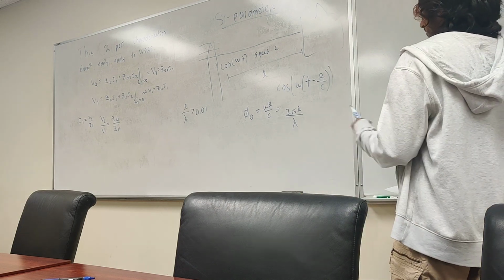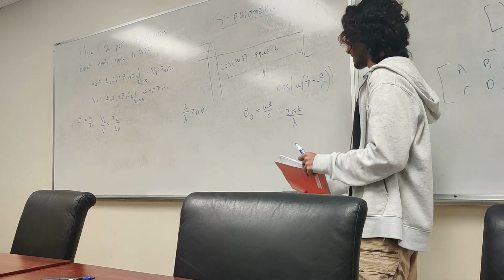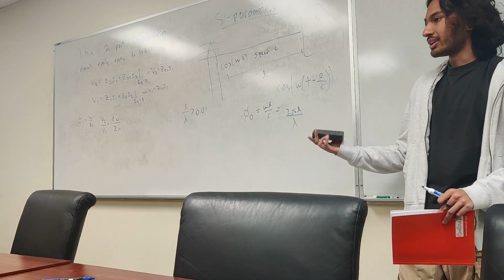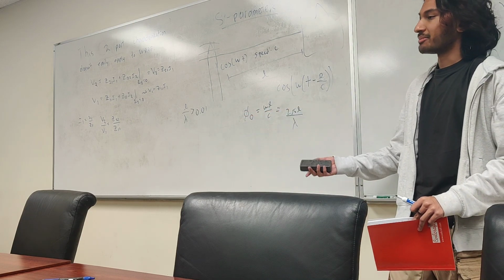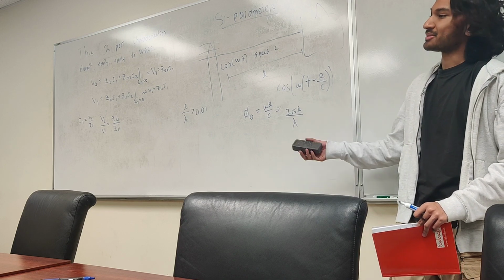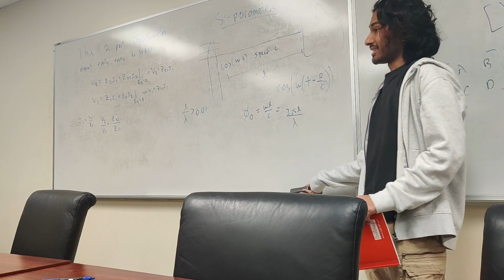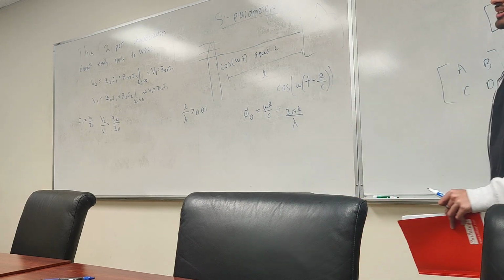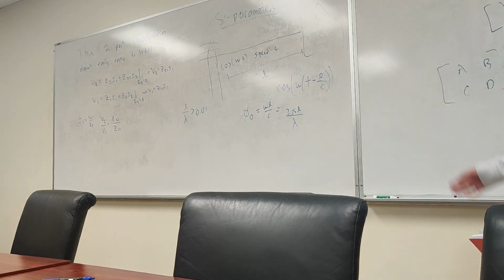So for RAP, we're at 27 megahertz, and our boards are half the size of this. Do we care about transmission line effects? 27 megahertz, something this size? Absolutely not. For gigahertz things, sure. But for RAP, we don't. So why am I even bringing this up to begin with if we don't care about it for RAP?